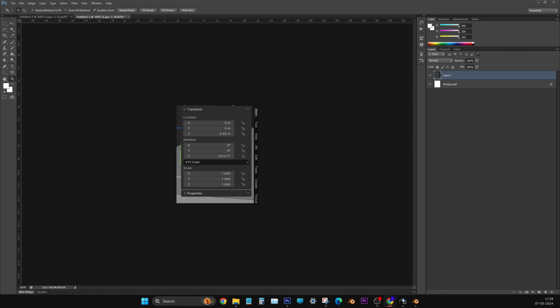Yeah. So just keep it on the vertex. Now, without using the handle, you can use free move, the white color circle. With that, just move near that upper vertex. When you take it there, it will snap.